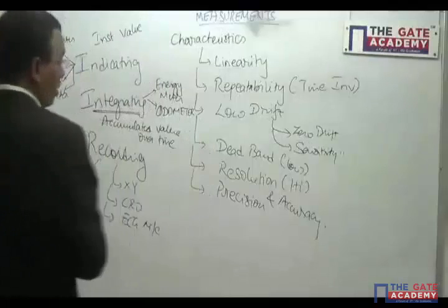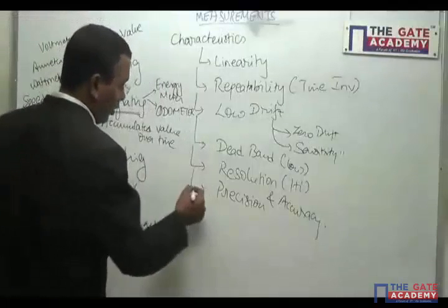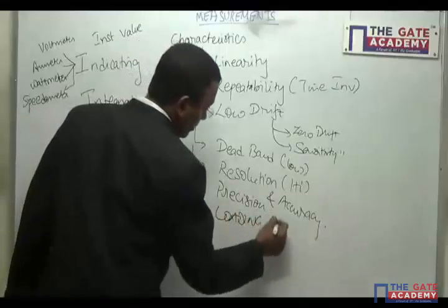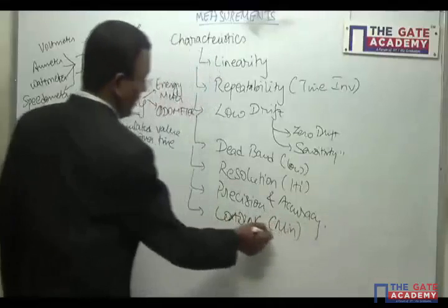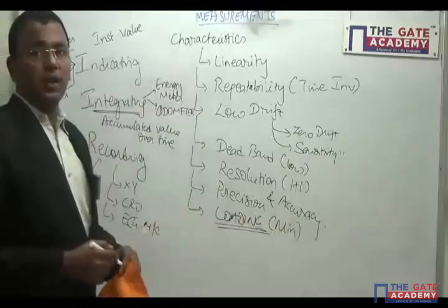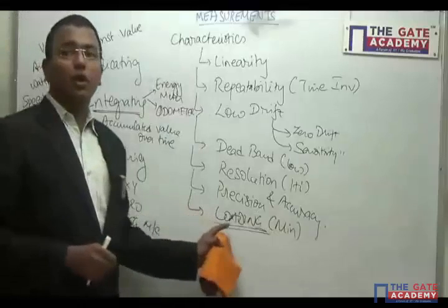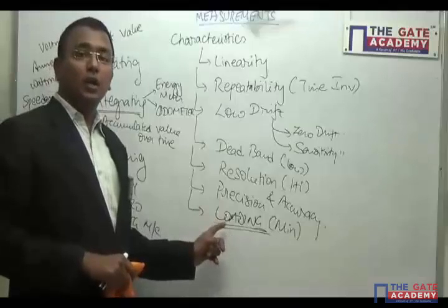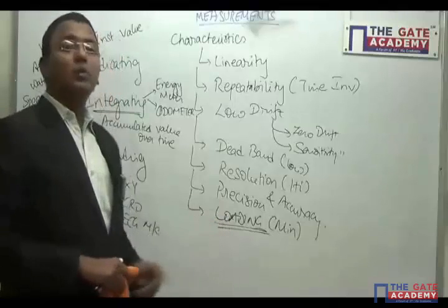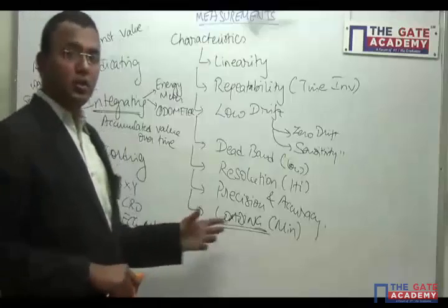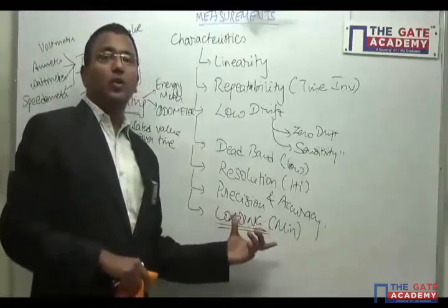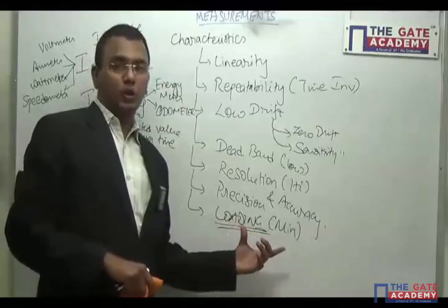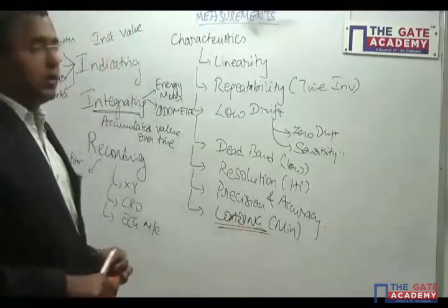electromechanical instruments. And one important property we also saw here was loading. We want loading effect to be minimum. That is nothing but abstraction of energy for working. We also saw examples, and we also saw why electronic instruments are superior compared to your electromechanical instruments when it comes to loading, because electronic instruments have power supply to work, so they take the energy for working from the power supply, not from the input. These are the properties we discussed yesterday.